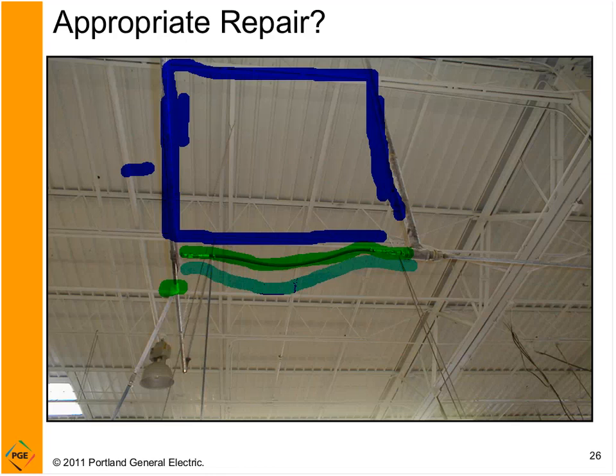The trouble with this is, and there are really a couple of problems here, the hose itself is a very small rubber hose, and not a lot of air can get through there, and then there are the quick disconnect fittings on the ends. These things can be small, poorly designed, and not allow a lot of air to flow through. So that's an opportunity there, I think. So pipe it in. If you're going to connect one pipe to another, put it in with the same size line at least. Let the air get from point A to point B to better serve the end uses.